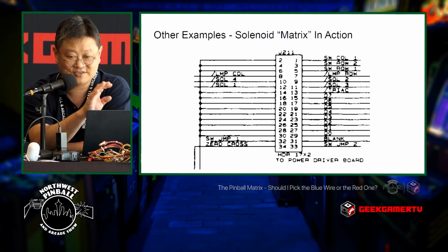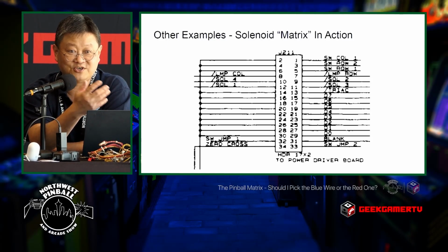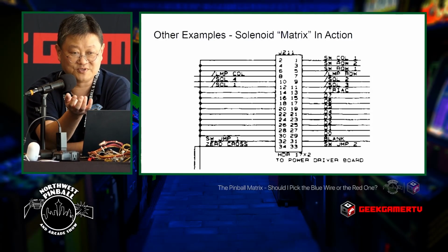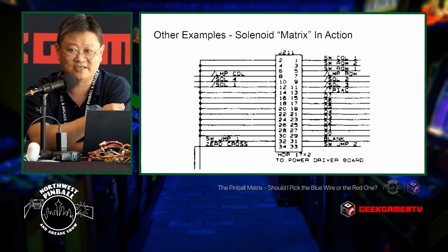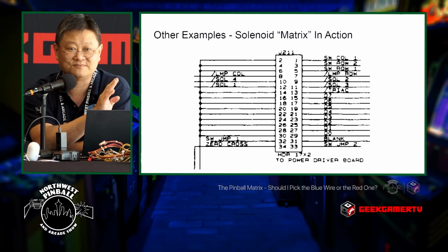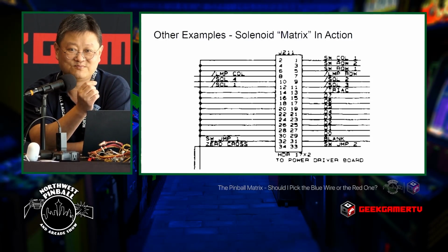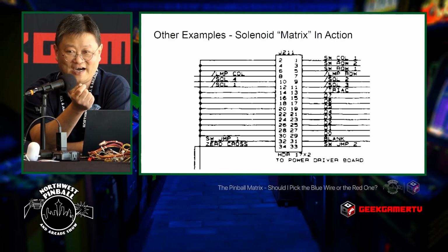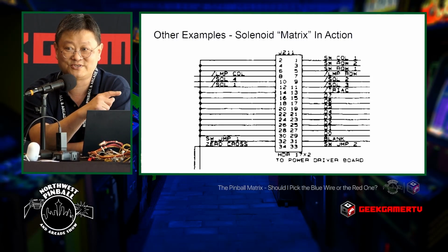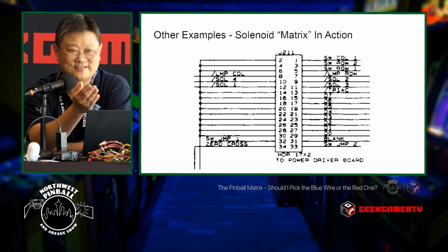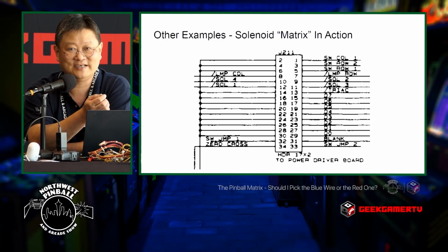And Sol 1 says, I'm just listening on the data bus for the Sol 1 signal. When it sees the Sol 1 signal, it pulls the 8 data bits off the bus and says, oh, you want 5 because you lit up D4? No problem, I'll do it. But if you don't light up Sol 1, it ignores it. So in this case, let's say you want to light up 13, which happens to be 5 plus 8. It will set the same bit 5, D4, on the bus, but instead of lighting up Sol 1, it will light up Sol 2. There's a chip there that's listening on the data bus that says, oh, Sol 2, that's for me. It then takes the 8 bits off the data bus and says, oh, bit 5 is on, let me energize solenoid 13.